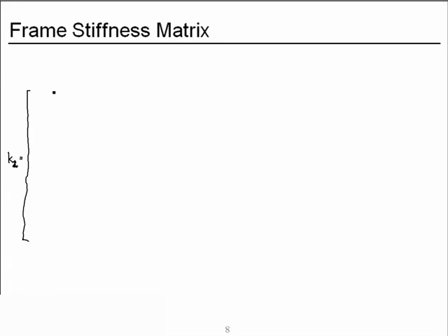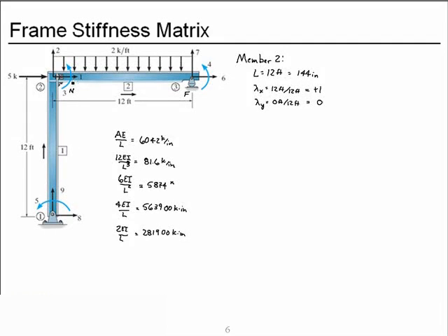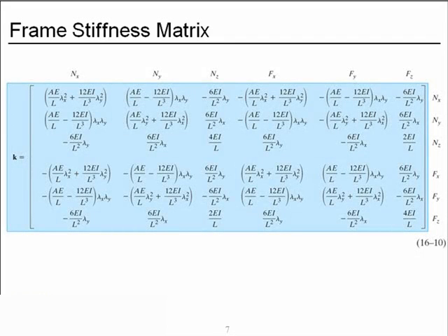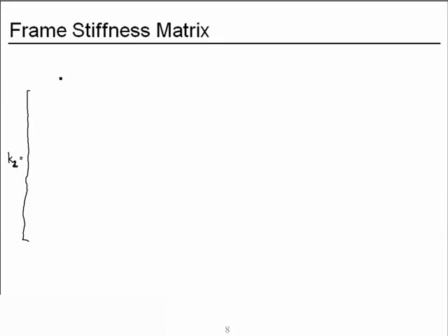And our degrees of freedom for the near node are in the sequence 1, 2, 3, and then the far node 6, 7, 4. And the sequence I counted them out at are set by the headings on our formula. I chose to number my original degrees of freedom that way because it will make application of the stiffness method a little bit easier for me, but we'll see that in the next example problem.